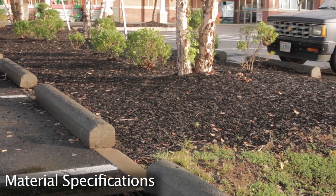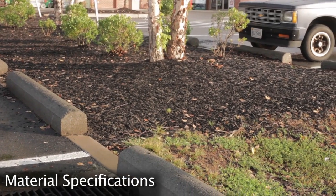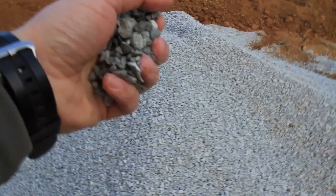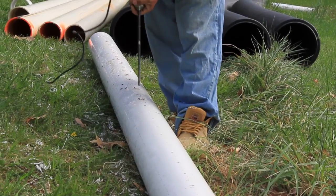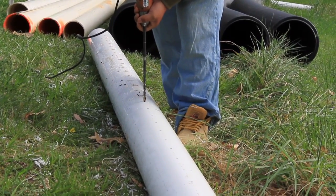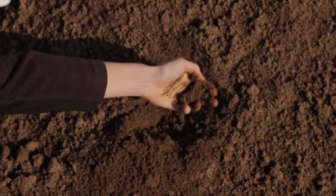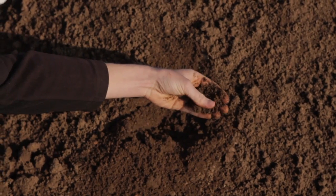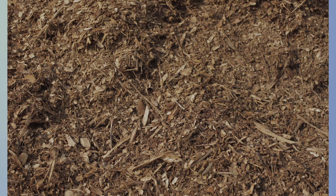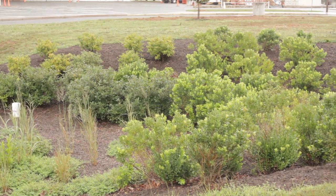Next, material specifications are an important component in BMP installations, and one of the most common missteps in the construction process is using improper materials. Ensure that the stone being used is washed and the correct size. Use pipe material that is the correct diameter, schedule, and material. Confirm that the soil or sand is the correct mix, and use the appropriate ground cover, mulch, and plant material. Let's hear from Steve Seal.